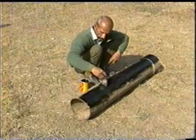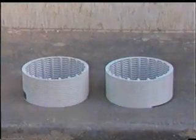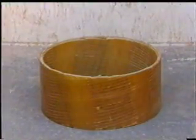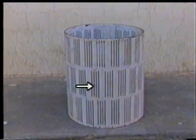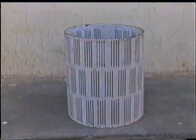Alternatively, corrosion-resistant pipes such as rigid PVC pipes, fiberglass, and stainless steel, etc. could be used. Under corrosive conditions, well screens should be preferred with large open areas and comparatively thicker pipes coupled with low rate of pumping.